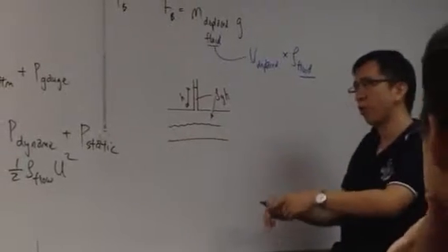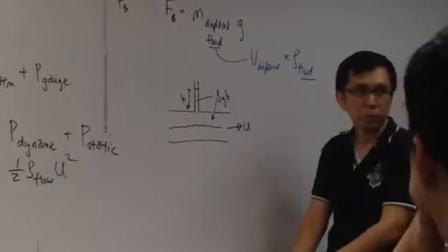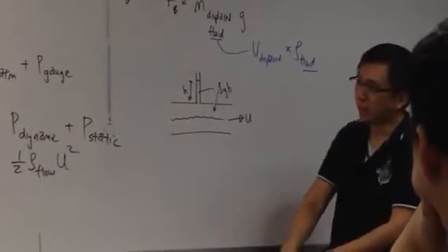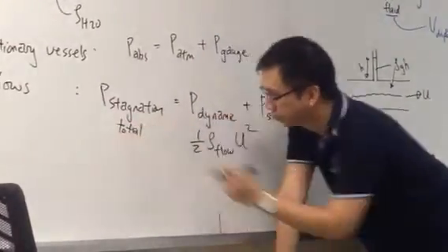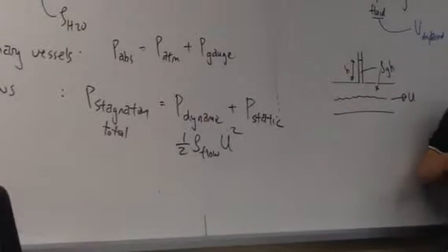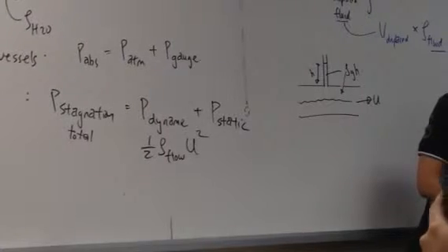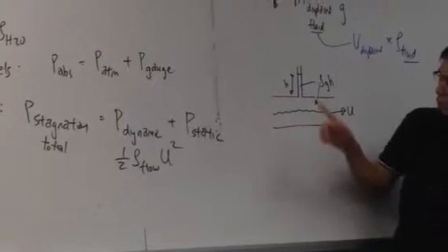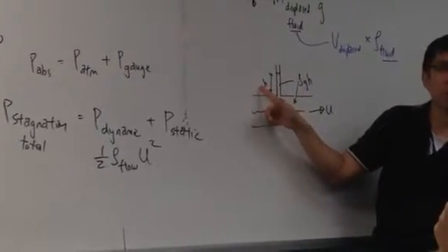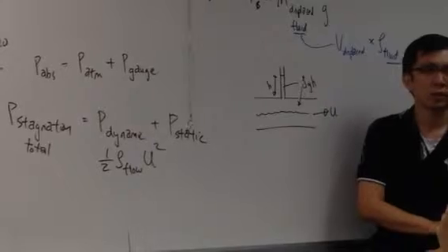To put it simply, for dynamic pressure, they will often tell you the speed, then you just multiply it in to get the dynamic component. Stagnation is also called total pressure. Usually they will sometimes give you a certain height, or they just straight away tell you that it's some kilopascal of pressure. That is your static pressure.